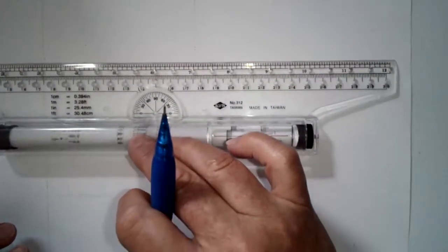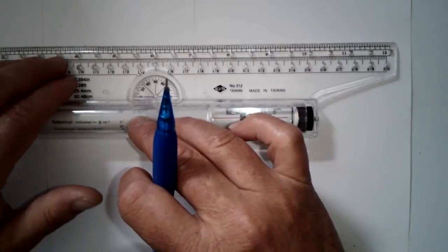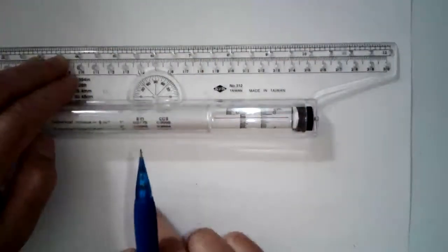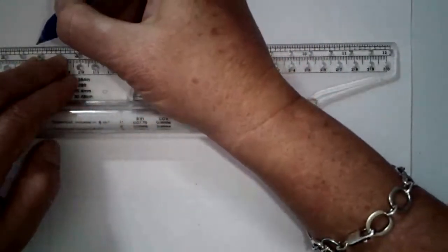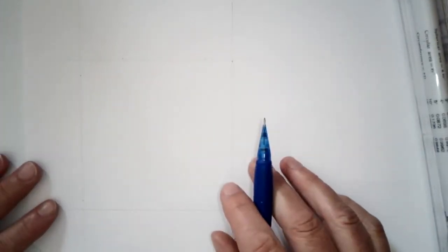And you can test your rolling ruler to see if it's staying parallel. That's perfect. See, that lines right up with those 2 dots I created by lining it up first with the first horizontal line, and then I know that things are staying parallel and perpendicular. So now I've got these really light construction lines, and they tell me everything I need to know in order to place my actual object lines.